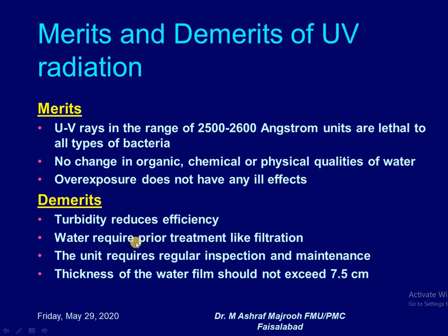The water requires prior treatment like filtration. The unit requires regular inspection and maintenance. The thickness of the water film should not exceed 7.5 centimeter. If the thickness of the water column is increased, then the UV rays will not be effective.